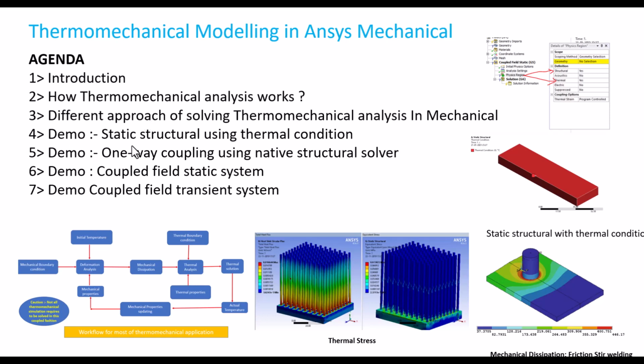For example, a demo in which we will discuss static structural using thermal condition. Then we will go towards one-way coupling using the native structural solver and APDL thermal solver. Then a demo of a coupled field static system, and finally we will also see a demo of a coupled field transient system.